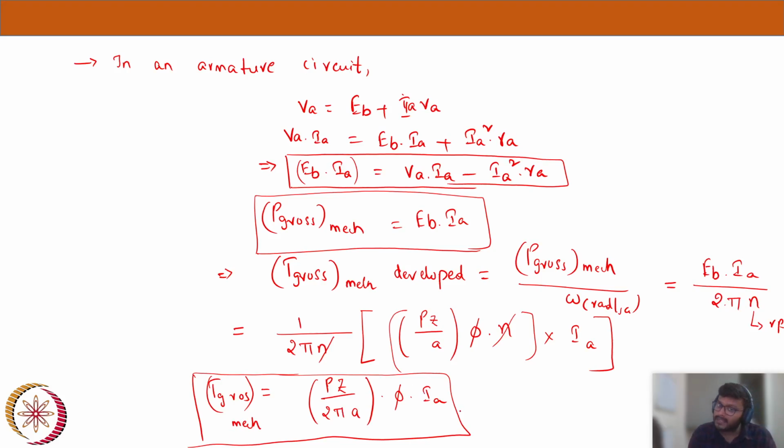We also derived the same kind of equation along with the EB equation. We took the force experienced by each conductor, calculated BIL for each conductor, and multiplied it by the total conductors in that machine to get the torque developed. So again, we came to the same equation here. I'm just justifying these governing equations of a motor.